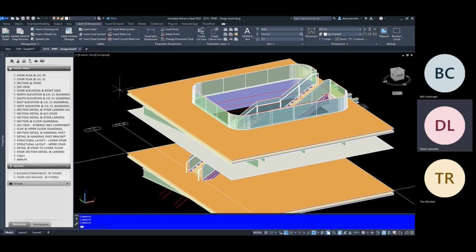Advanced Steel really relies more on the use of macros to generate your stair shape, heights and everything else, and you would modify the macro to automatically resize the stairs as per your requirements. It may not be able to do everything that you want it to do. So you definitely don't have that flexibility that you would have with SolidWorks or Inventor.